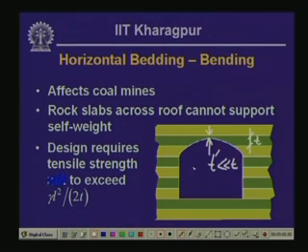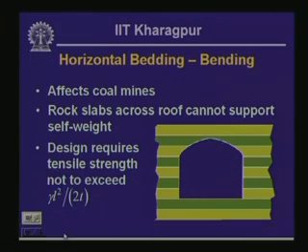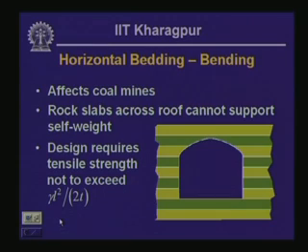As a result, the stability of the slab near the crown is going to be compromised quite severely if this type of tunnel cross section is chosen. So the bottom line is in this case a square cross section of the tunnel is preferable.